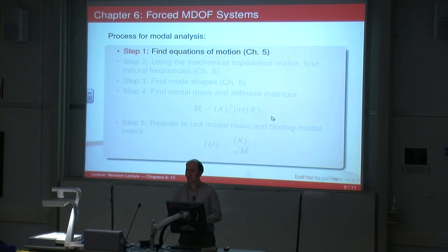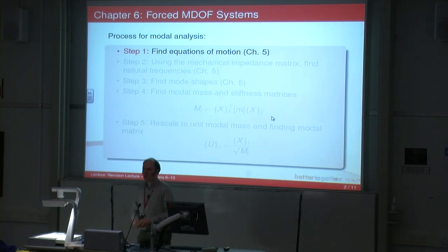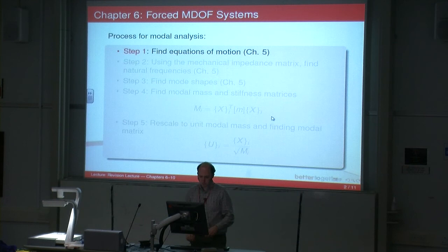involved using this thing called the modal analysis technique, or modal analysis, where you basically instead of trying to solve simultaneous differential equations, you can separate it out into equations that represent the modes of the vibration, and then you can convert it back to displacements.